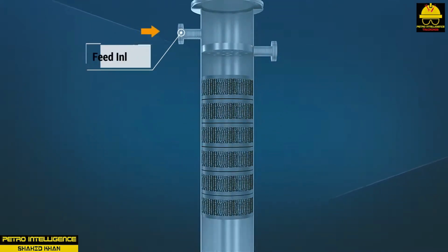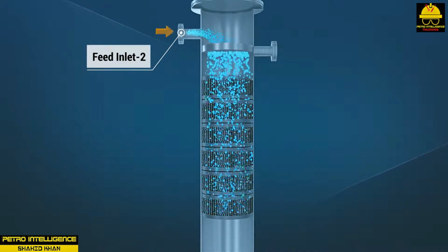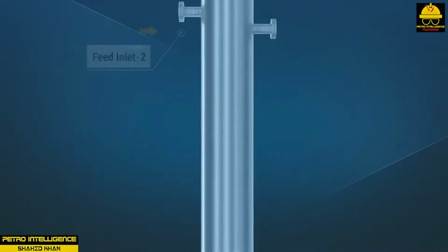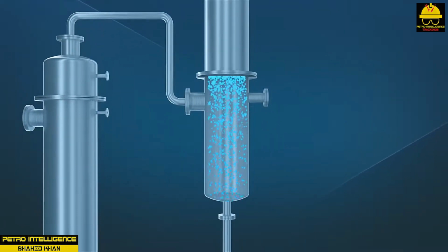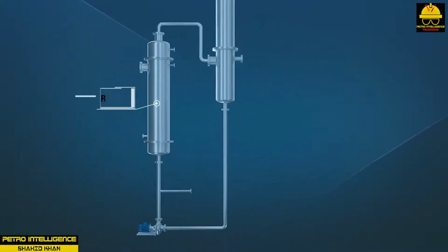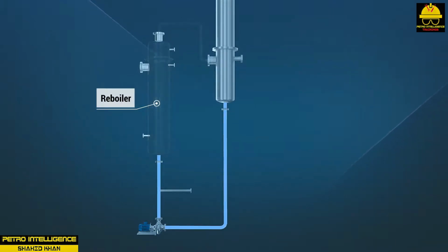A variety of arrangements is available on the distillation column to condense the hot vapors and collect and separate the distillate. The bottom system is composed of a section in the column designed to allow liquids to boil and roll freely. A reboiler is connected to this section to maintain and add heat energy into the liquid. The term reboil indicates that the liquid was originally boiling. Hot vapors are returned from the reboiler to the bottom of the column below the bottom tray. A level control loop is used to keep the liquid at a predetermined level. In the bottom system, liquid level, temperature, and composition are carefully controlled.